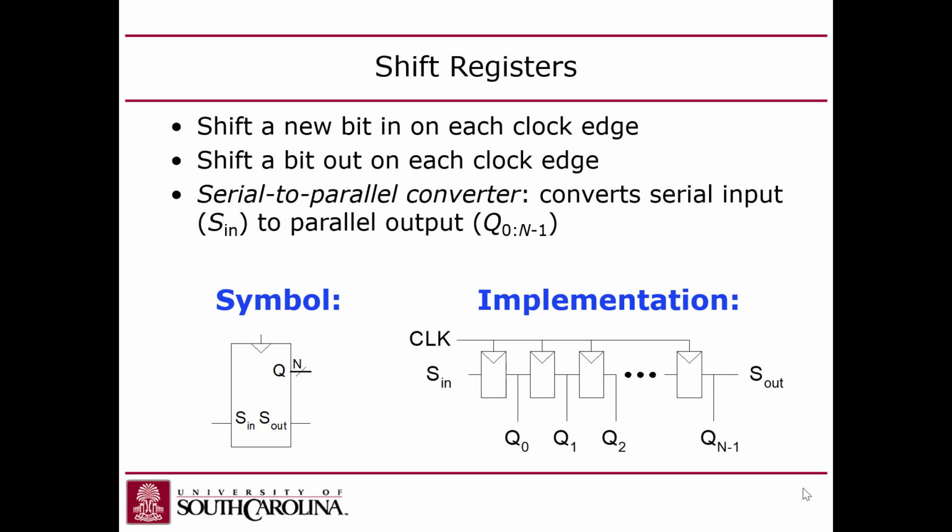Okay, timing constraints. But yeah, we used to have, Charles, did we still give them the code for the DE2 board that did the shift register? Yeah, that was for the bouncing light. Yeah, except that was in Verilog, so you don't directly connect the D flip-flops in series, because this is what would get synthesized from doing the shift by 1 operation in Verilog.